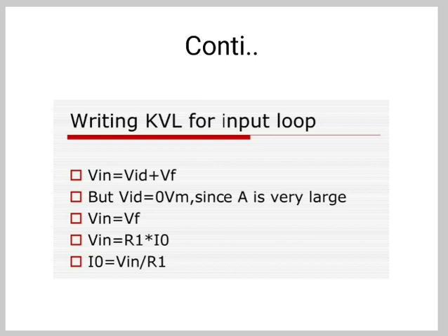Here the feedback voltage is determined by the load current and it is in series with the VD, which is the input difference voltage. So this circuit is a current series negative feedback amplifier.